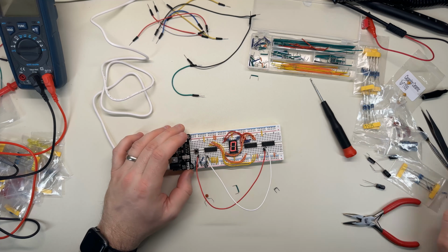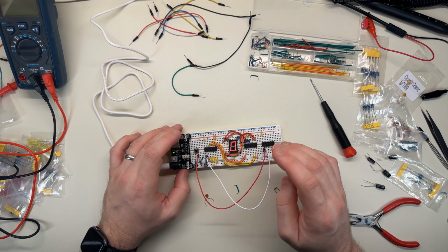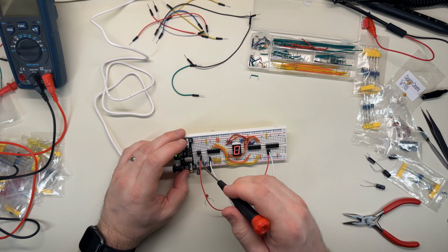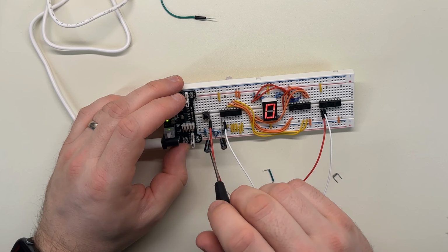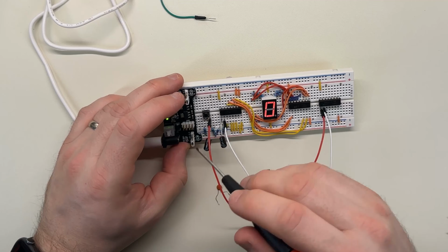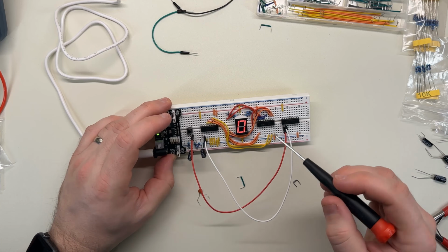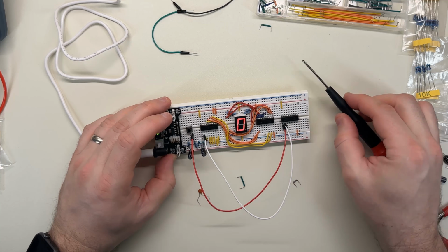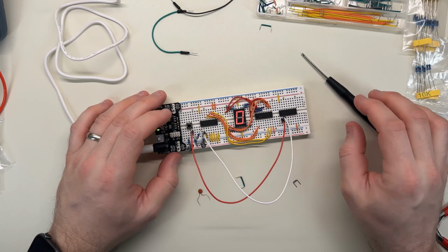It's also the article, maybe not part 1, but one of the parts in this series, that really pointed out that issue of needing this other resistor here, because when you discharge your switch, that current has to go somewhere, and how much current that is. It's way more than you would think, but that's because it's such a short time period and there's no resistance there, or nearly no resistance.